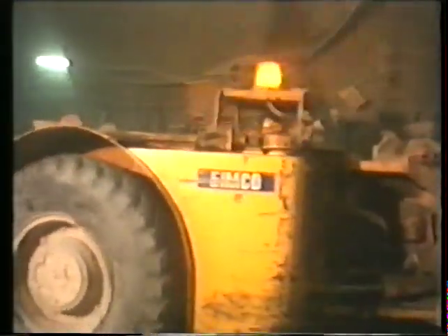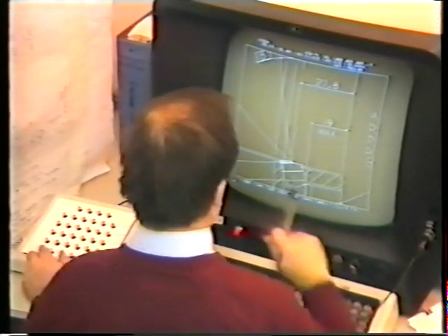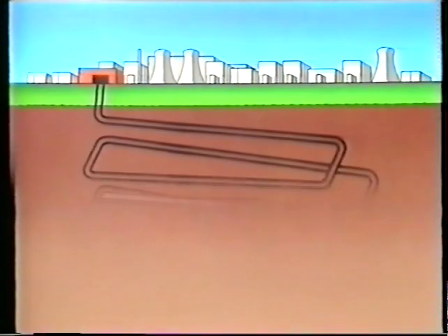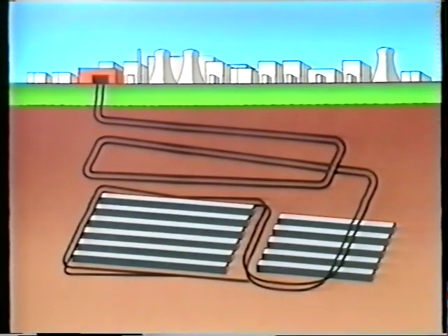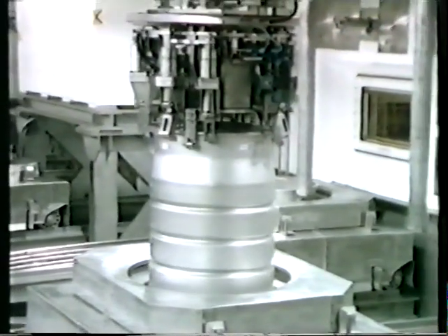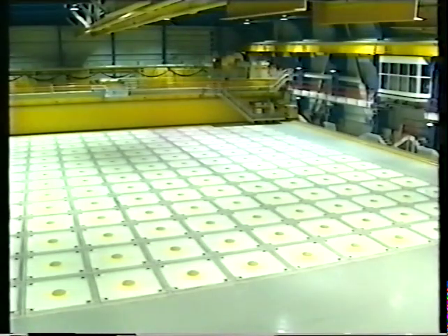Researchers are testing stable rock 500 to 1,000 meters underground. They are finding out if underground water will become contaminated and are checking the long-term effect of heat on the rock. The most acceptable method of disposal is underground in stable rock formations. In the UK, intermediate level waste includes the cladding stripped off the outside of the fuel rods. Usually, it is encased in concrete inside stainless steel containers. These too await permanent storage.